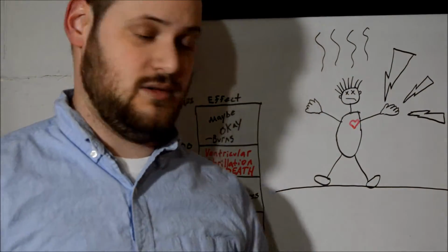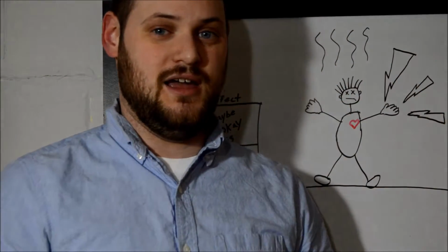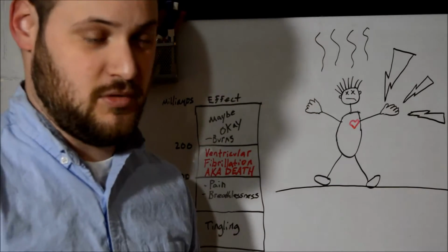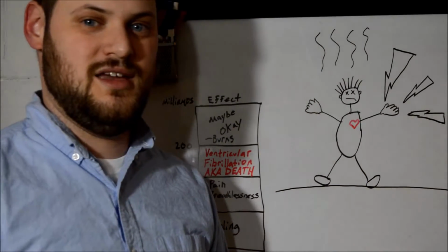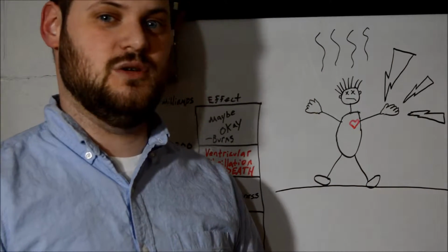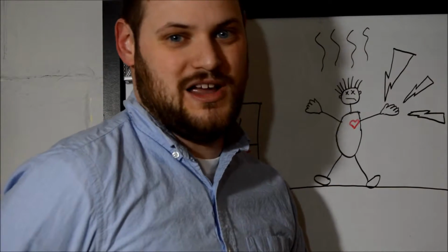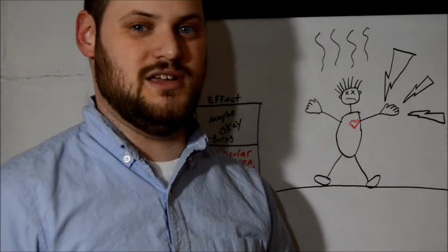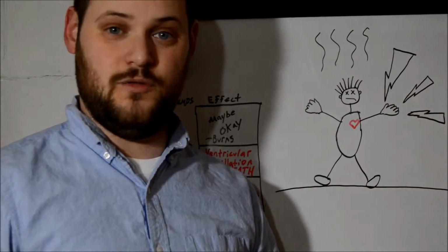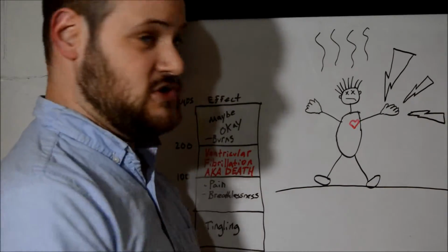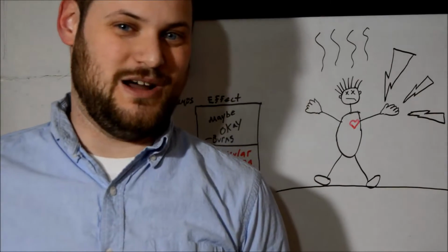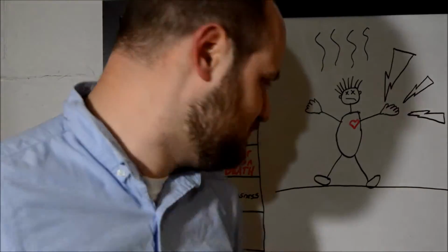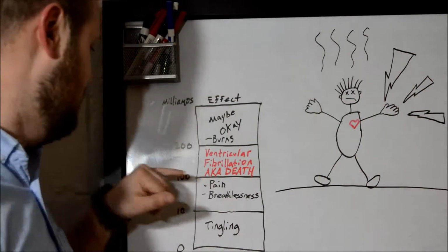The worst case scenario is actually from hand to hand, and for electricians that's very dangerous because they're often working with both hands. That's why they tell you when you're doing electrical work, put one of your hands behind your back. It lessens the risk that you're going to get a fatal shock. Although if I could give any advice based on what I just told you, keep your left hand behind your back. Sorry, lefties.